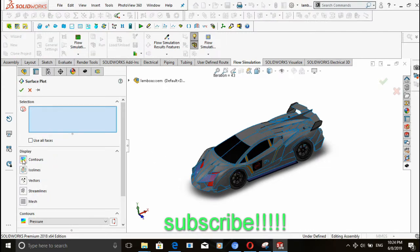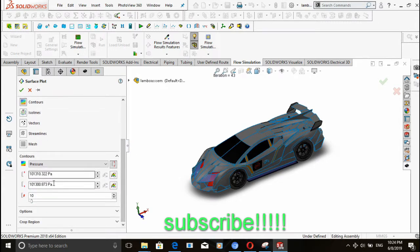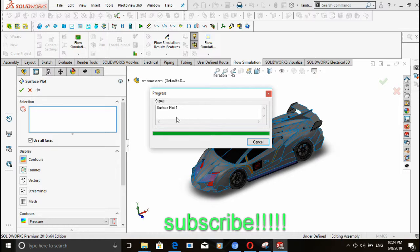Now I'm just going to choose contours. I'm going to choose all the surfaces, choose contours, and we're going to see the maximum and minimum pressure that has been given here. So we are going to leave these values as they are by default. We're going to click this and allow it to calculate. Like I said, it depends on the speed of your computer. We're going to see what we obtain at the end.